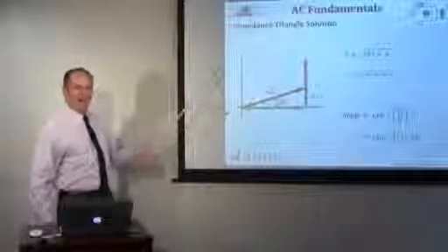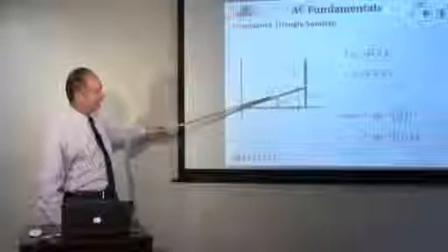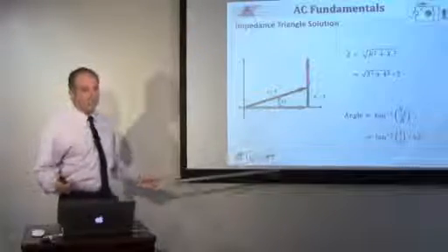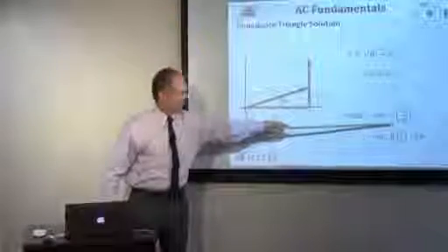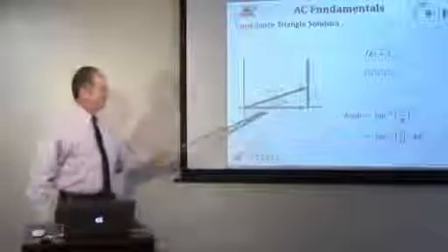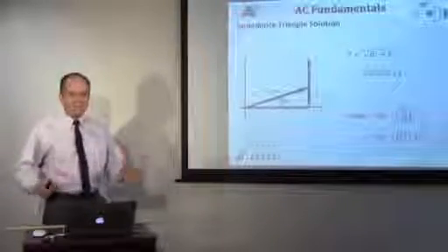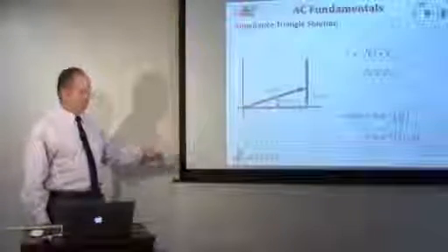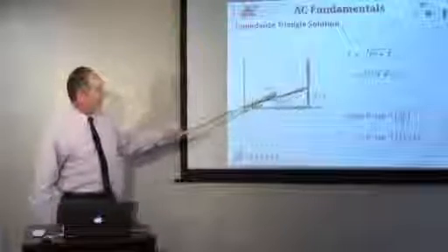This 5 is known as VA, and we're going to get into that shortly. If we want to calculate the angle, we go into trig and say that the angle is the arctangent of XL divided by R, 53 degrees. A little bit of math there if you needed to calculate an angle. The important part here is if this is R and this is X, this is Z.